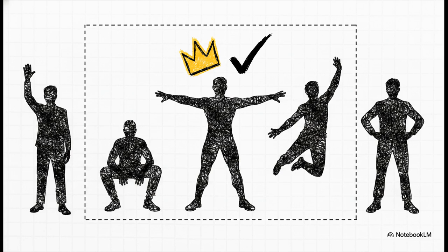So before you even think about adding any complex extra controllers, you need to create 5 or 6 hero poses. And here is the real kicker. You have to view these hero poses entirely as silhouettes. Turn off your lights, turn your materials black, and just look at the shape. This is your foundation right here.